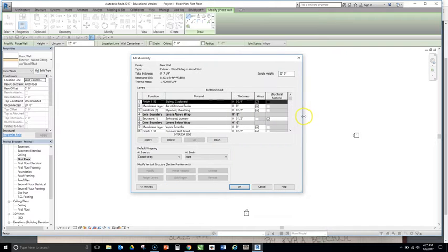we can see that the structure of the wall is softwood lumber. That's 5.5 inches thick. In other words, it's 2x6 construction. There's a 1/2 inch layer of plywood sheathing and a 3/4 inch layer of siding on the outside of that. On the inside of the wall, there's 1/2 inch drywall. These two gray layers here represent the core boundaries of the structure of the wall.